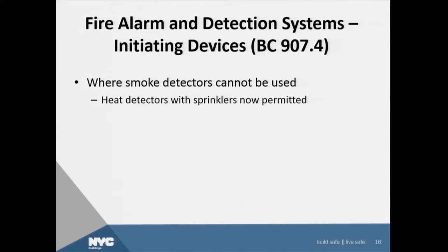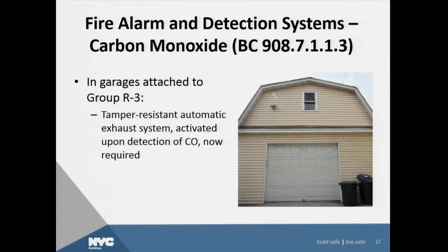Okay, so there's a new provision also that makes it a lot easier to substitute a smoke detector in a building with a heat detector, if it's something where the accidental activation could be caused by the types of equipment or the types of uses in the room. And here's a provision, and we will be working on some guidance soon with a buildings bulletin to describe what this is.